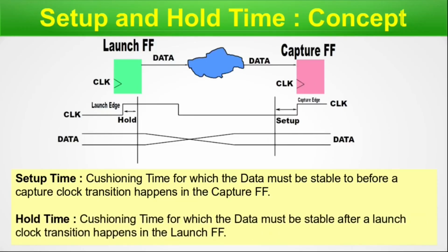Hold time: the cushioning time for which the data must be stable after a launch clock transition happens in the launch flip-flop. So now let us come to the launch flip-flop, and we are talking about hold time here. You can see this particular cushioning time after the launch edge of the clock has arrived.